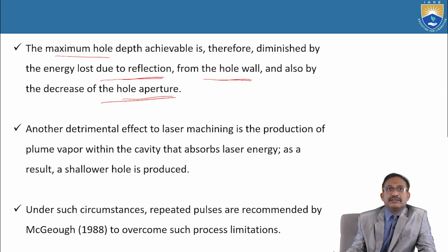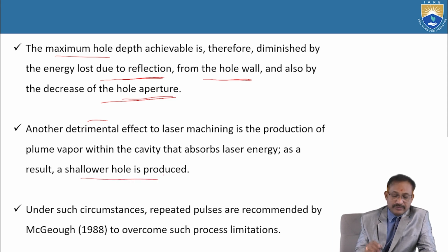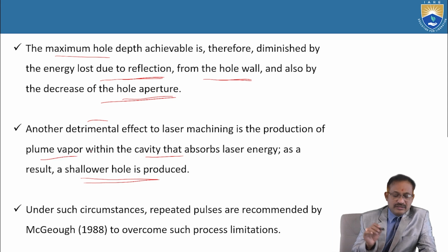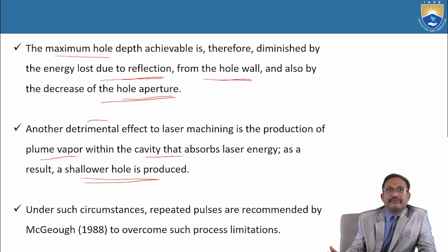Another detrimental effect to laser machining is the production of plume vapor within the cavity that absorbs laser energy. As a result, a shallower hole is produced. A shallower hole will be the result because of the cavity and plume vapor.